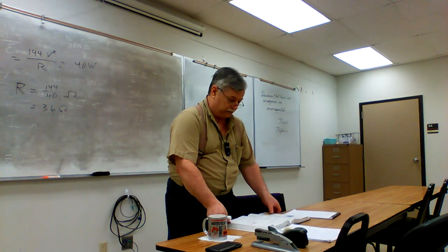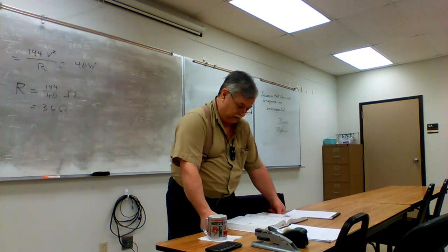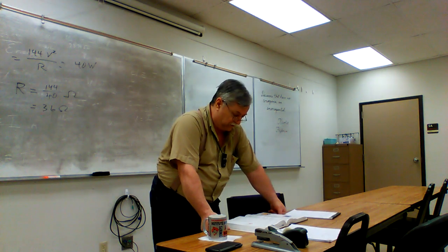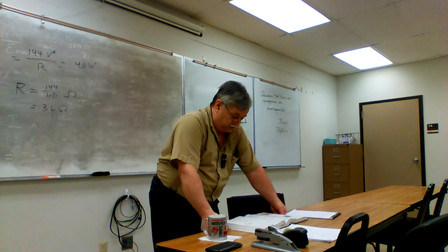Let's start by working through the example here, 18.9, an electric heater. It's 15 amps on a 120 volt line. The electric heater draws a steady 15.0 amps on a 120 volt line. How much power does it require, and how much does it cost per month, for 30 days, if you operate it 3 hours per day, and the electric company charges 9.2 cents per kilowatt hour, which is pretty close to what they charge around here.